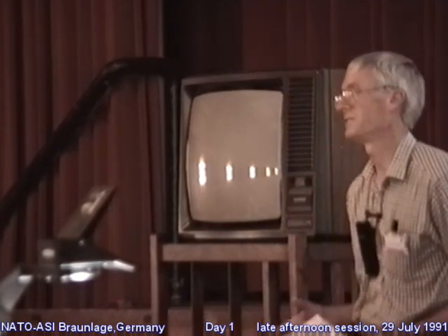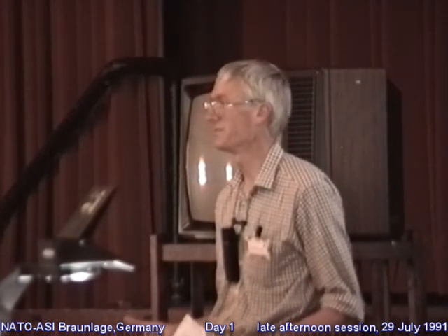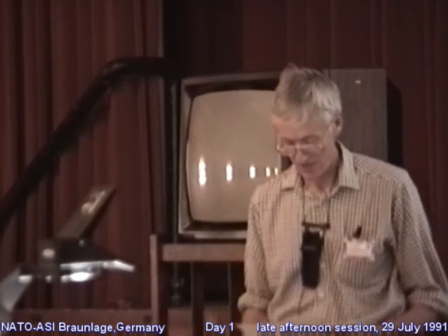The force of attraction is not proportional to the contact area. For anyone who has not met the ideas of fracture mechanics, this perhaps is surprising. If I have a sphere against a flat, and I double the contact area, I might expect to have twice as much force. That's not the case. What I'll try to show you is that the force varies as the 3/4 power of the contact area. So there it is.